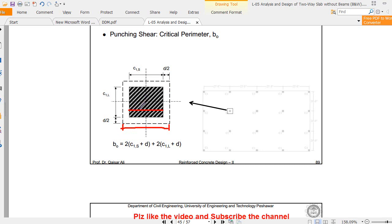C1S means the shorter side of the column, C1L the longer side. So this side will be C1S plus d by 2 and d by 2, so C1S plus d, because d by 2 plus d by 2 gives d.